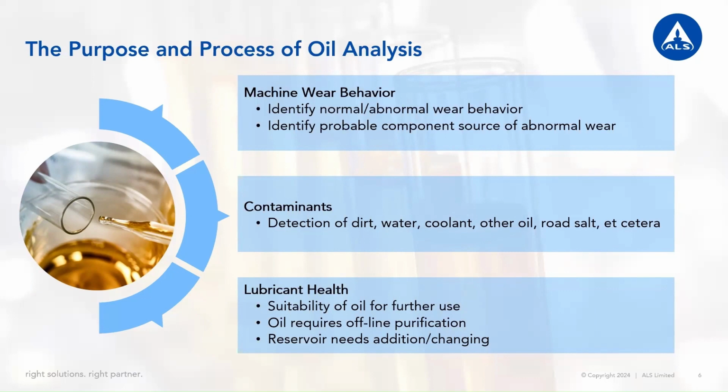Finally, lubricant health monitoring is critical in understanding how your equipment is faring. Knowing how your lubricant is performing can give you insights into how long a drain interval can be, whether your system needs to be filtered, and whether the oil you selected is even performing as advertised.